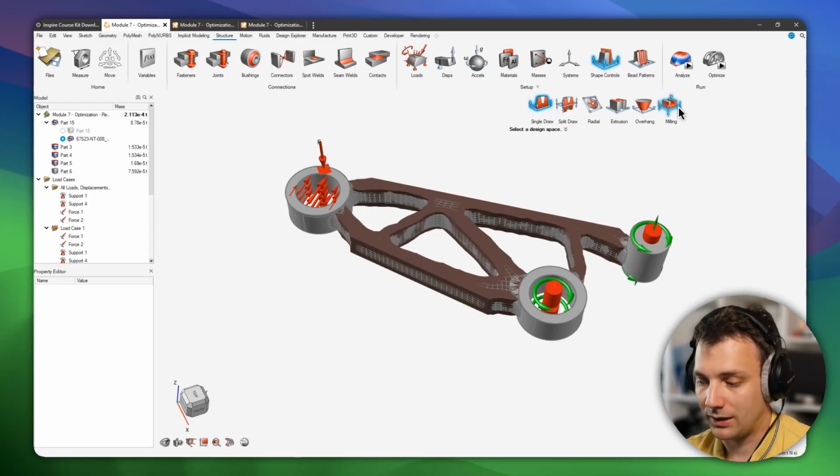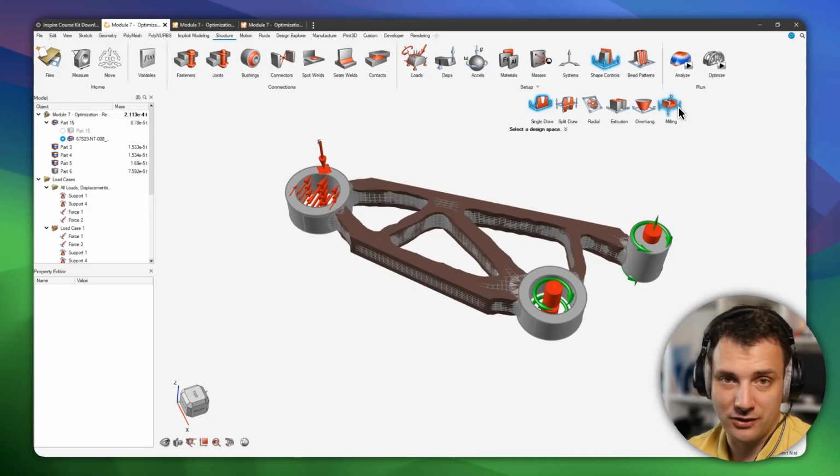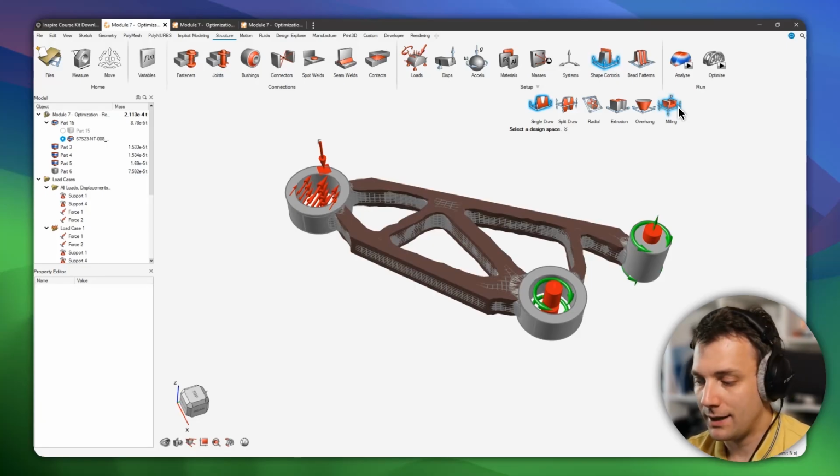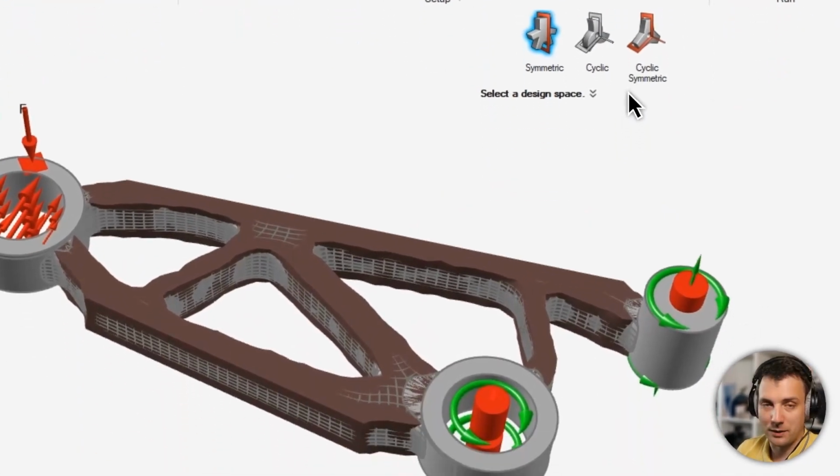So basically those shape controls help you design constraints on the structure which comes out of the optimization, which makes the part manufacturable for traditional manufacturing. For 3D printing, you have the overhang constraint, but then that's it, right? So a 3D printed part has no problems with those kinds of undercuts, as they are called. So basically, those are shape controls you could use to make the part manufacturable, and they help you greatly in designing the structure afterwards.